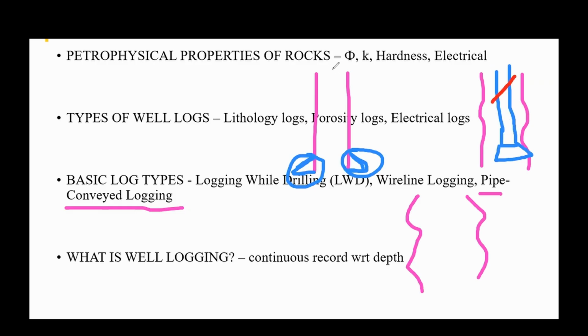Or during your well logging operations, the sonic tool can be lost. Sometimes the wire can be cut, and this tool can be left in your wellbore, falling into it. At that time, we want to retrieve these tools. We can't simply leave them in the wellbore. So these tools should be retrieved, and those operations are termed as fishing operations.